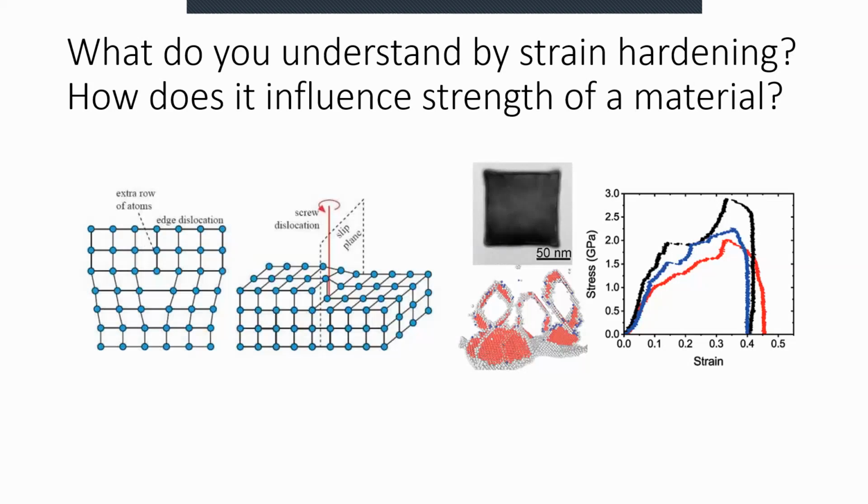Now the fourth moves to the fifth and it continues. In other words, this dislocation keeps on moving with continuing force from the left. This is a half plane, an extra row of atoms, and in the half plane there is a missing plane.